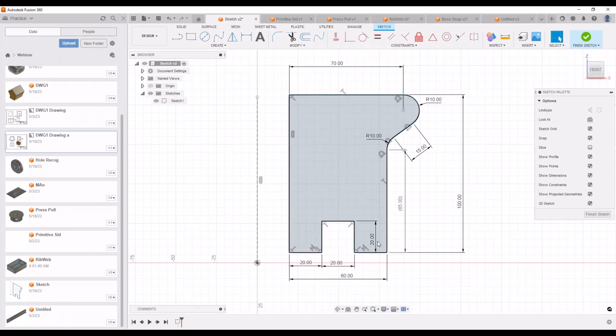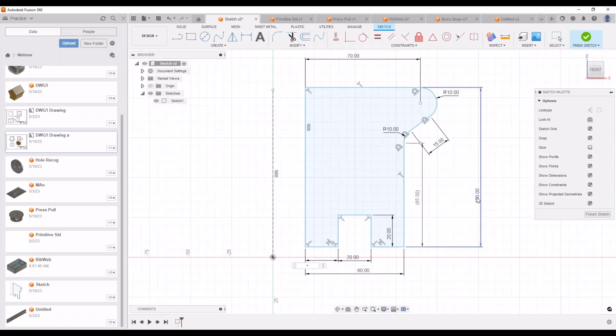So, for example, you can start taking these values here and linking them via equations. For example, that is one fifth of that. So you can take that and say it is equal to that one divided by 5. Parametric modeling. There we go. When you set that up, you see that the fx is shown, meaning it's a function of something else, and it's an equation-based value. So every time this changes, the height of the model changes, and the length of this section here will change accordingly. So if I change that to 80, that becomes 16, and so on.